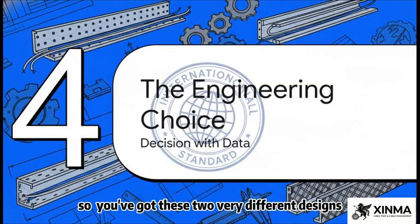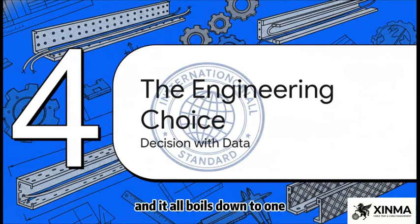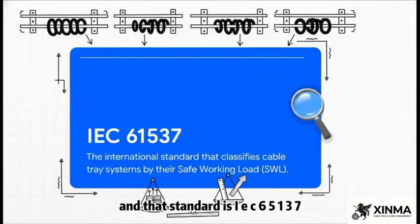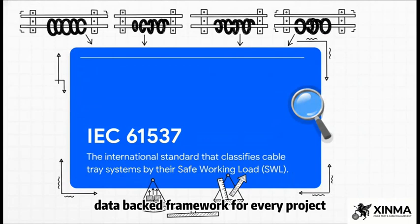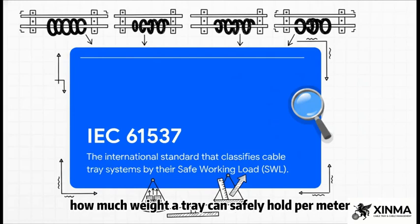So you've got these two very different designs. How in the world does an engineer actually choose between them? Well, it's not a guess. It's not a gut feeling. The decision is driven by data, and it all boils down to one single international standard. And that standard is IEC 61537. Think of this as the rulebook. It gives engineers a clear, data-backed framework for every project because it classifies trays based on their safe working load, which is really just a straightforward way of saying how much weight a tray can safely hold per meter.